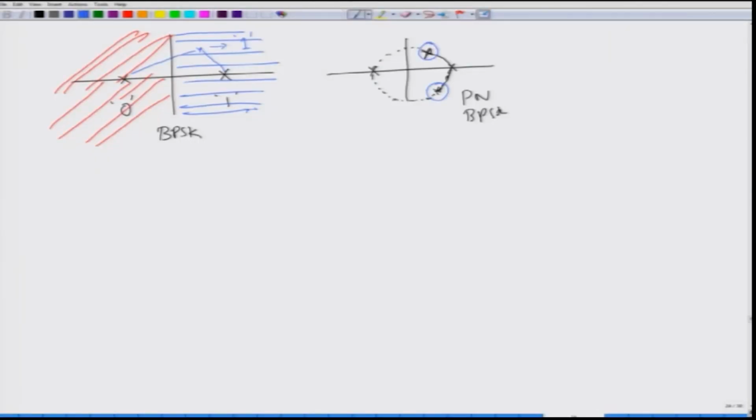If you add some ASE noise around that, then this would be the situation that you have. You have some ASE noise coming from the amplifiers, coming from the interaction of amplifiers with everything else that we will look at. Your received signals can be anywhere here, and of course, they can be rotated by this particular value. So, you see that with this received constellation you are still not making much of an error, and primarily the reason for this is because the phase noise is still manageable. It is only covering one segment over here.